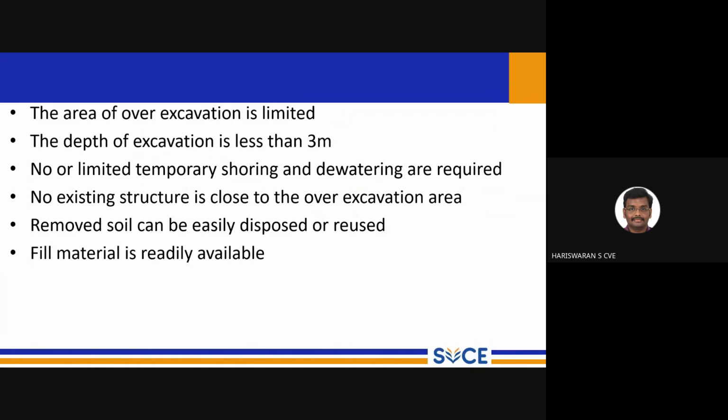Even if you are residing in a particular area, and near to that, a new structure is planned to be executed at G minus 2 or G minus 3, more care must be given. Only if they provide support should they excavate the soil. Otherwise, lateral mobilization of the soil can cause destruction of our own building. So we are supposed to give more care when such excavation takes place in and around our area.